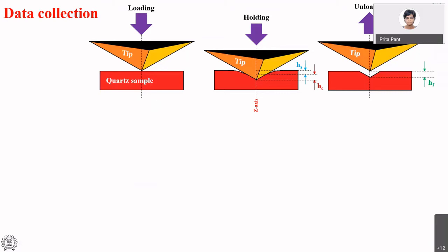the other part is in contact with the tip, but not actually touching it. This difference is very important, because when I said that we want to calculate hardness, it is HC that we are interested in. How much of the sample is in contact with the tip, because that's what is resisting deformation. The part HS, it deflects, but it's not actively resisting anything. It's just bent. You know, if you take a sheet and you try to poke it with something, it's going to deflect.